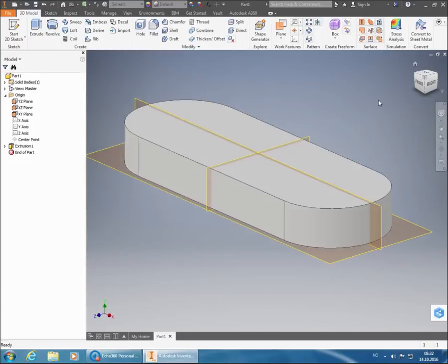That's not really a problem in this part, but sometimes it might be useful to be able to have the horizontal plane also centered inside your part. And I'll show you on the third one, this one, I'll show you how you extrude both ways instead of just one.